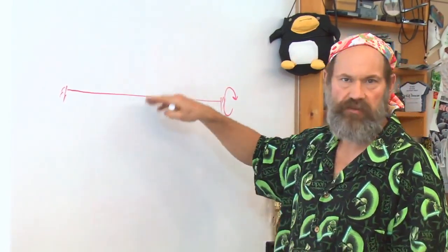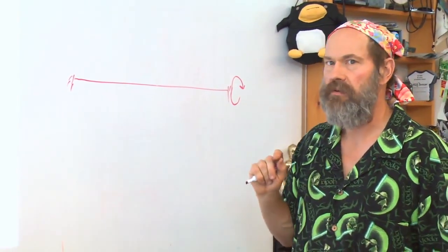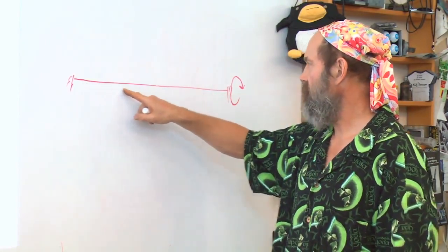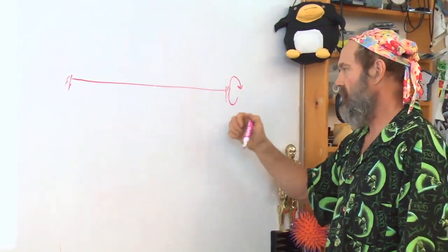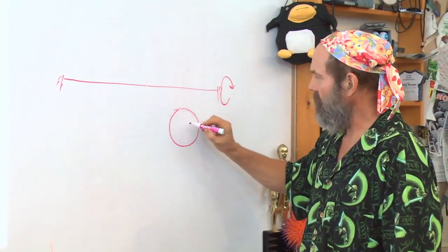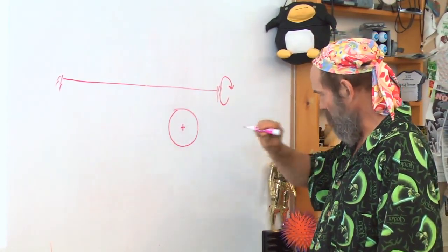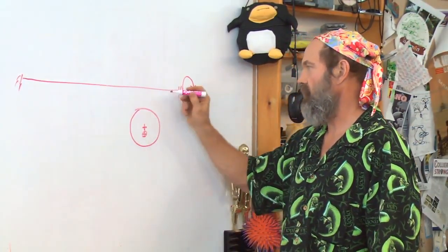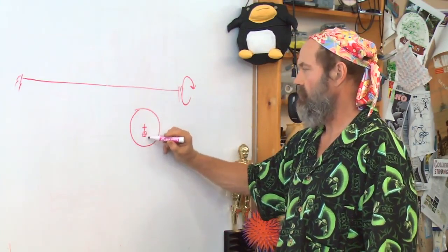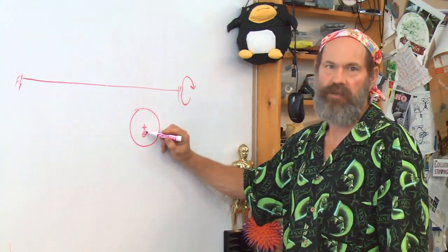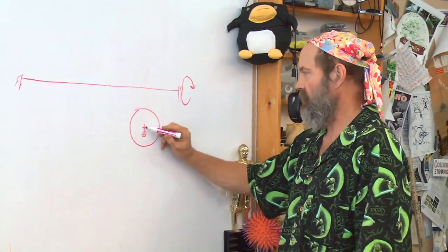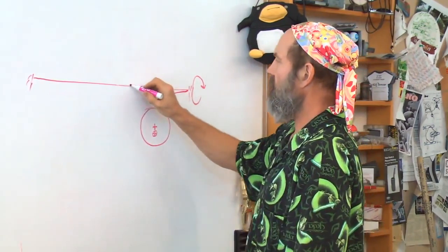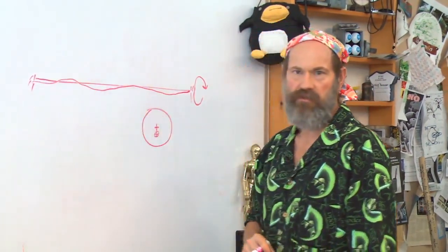Well, everything will have a natural frequency, and nothing is perfect. And this screw shaft, as I drew here, is not exactly straight. So that tells me that if this is the straight line, the average center, the center of mass of that screw shaft will, depending where I am along the screw, be somewhere off center. It just will be. Nothing is perfectly perfect. But whereas this line here is the exact center line between these 2 points, the screw center of mass will deviate because the screw can never be perfectly straight.